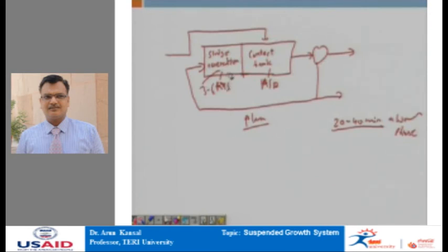During this period, the absorbed organics are used for energy and production of new cells. A portion of the returned sludge is wasted prior to recycle to maintain a constant MLVSS concentration in the tank.